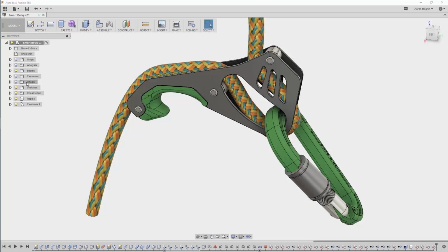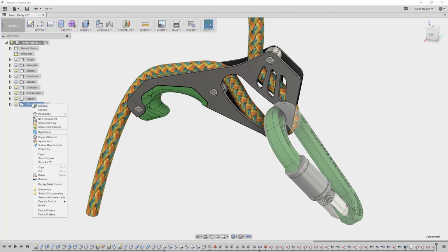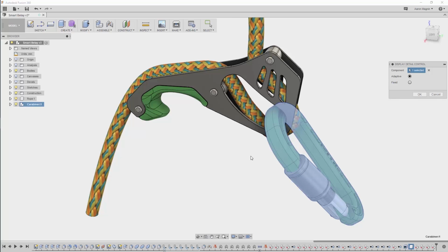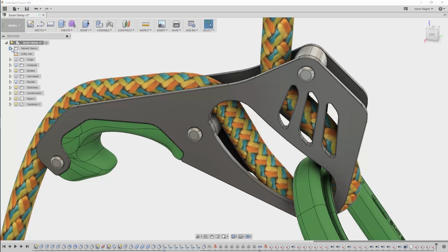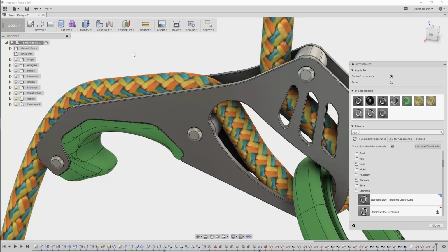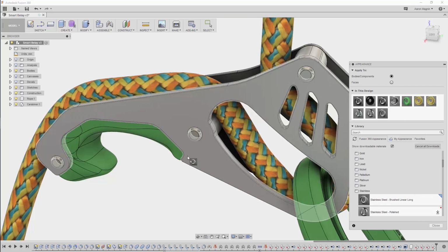And managing appearance quality and texture orientation was improved drastically with the addition of some entirely new options and controls. For instance, if I don't care to see every intricate detail of the carabiner because I'm really working on the belay device, I can use the display detail control to fix the detail level at a low setting. Imagine how this can help reduce the hardware overhead of large assemblies, or, on the flip side, enhance the viewing quality, rendering, and anti-aliasing of simpler models.